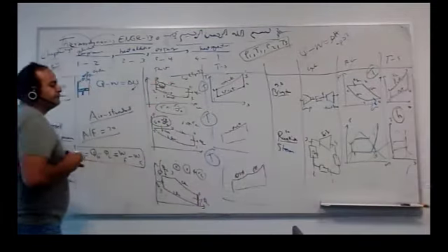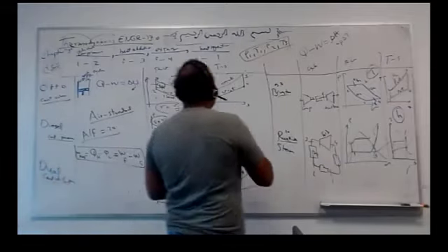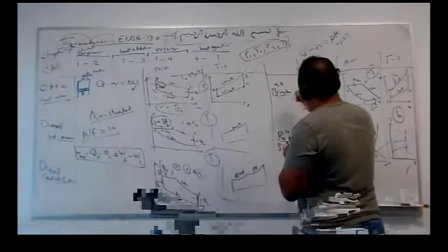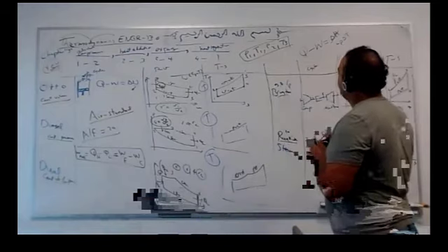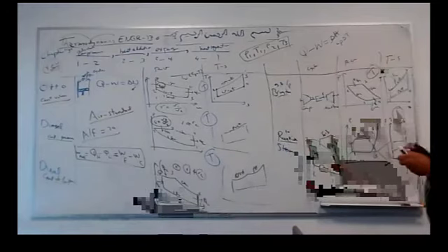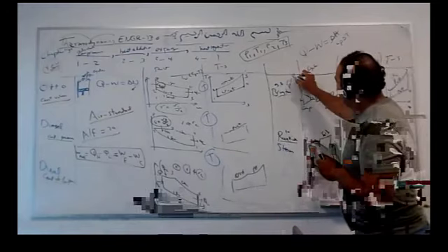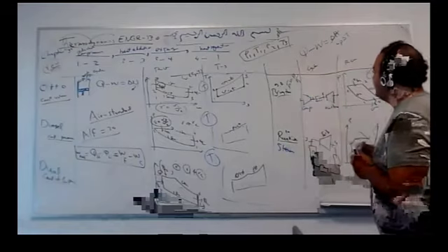Sometimes I don't need to give you T3. I can give you heat, Q high or Q low. I don't need to give you T3 explicitly. I can give you something else to calculate T3. Usually I don't give you, for example, V2. I give you rp, like pressure ratio, P2 over P1. The same here, rp, which is the pressure ratio.